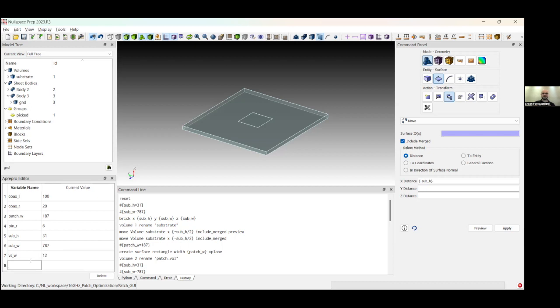We have done that, and now we can calculate what would be the length of the inner pin. The inner conductor will go through the substrate. So we need to include the substrate thickness plus the connector length, coax underscore L. And we want to remove part of it and have a gap where the port will be located. So we remove the port width, VS underscore W.